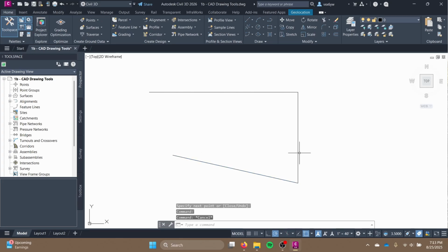You'll also notice it made these lines as different objects. You can see that as I select them, they're different. But it is possible to select all of the lines and use the join command. It creates 3 objects into one polyline, and now we have just one object.